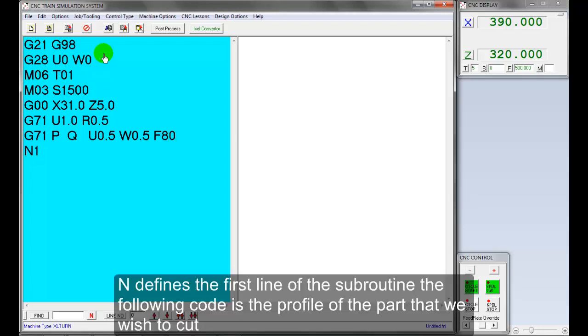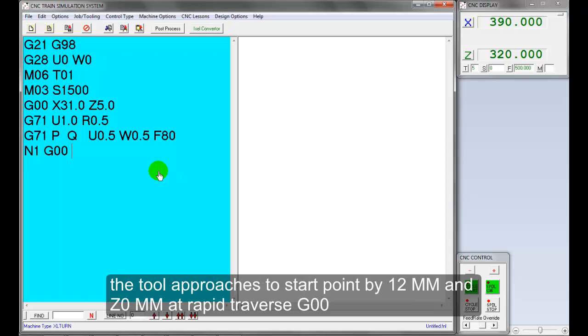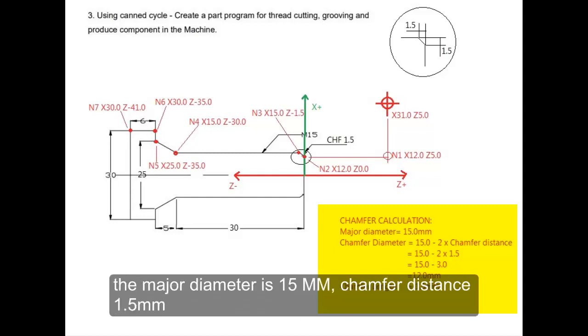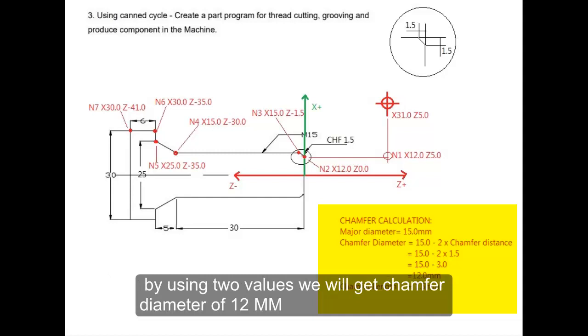N1 defines the first line of the subroutine. The following code is the profile of the part that we wish to cut. The tool approaches to start point X 12 mm and Z0 mm at rapid traverse G00. Please find the chamfer diameter calculation. The major diameter is 15 mm, chamfer distance 1.5 mm. By using two values, we will get chamfer diameter as 12 mm.